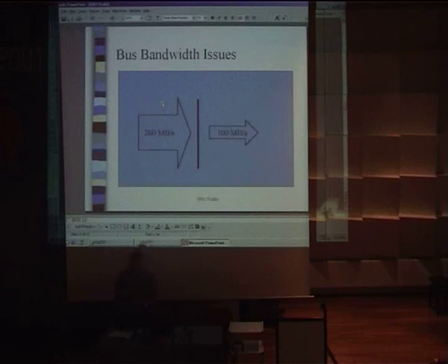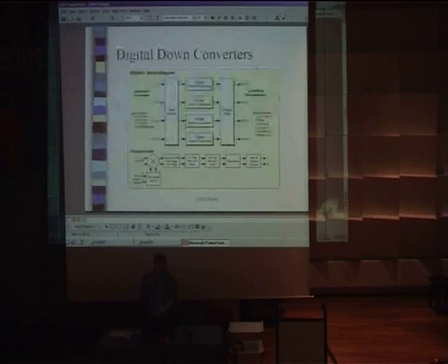And one solution that people have commercially used to solve a piece of this is these things called digital down converters. This happens to be a great chip part, but it has 4 of these channels. There are analog inputs, there are analog to digital converters out here, so then you have digital data streams coming in here. So this thing has a common front end, and then it's got 1, 2, 3, 4 channels, and then an output.